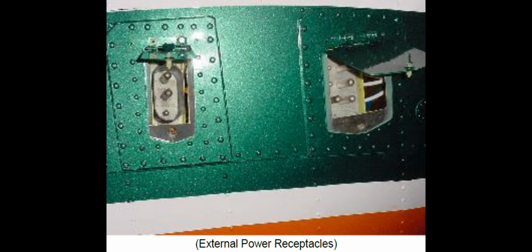If either or both generators are activated, AC bus loads will be removed from the auxiliary power unit and normal power will be restored. If external power does not meet the requirements of the external power monitor panel, a relay in the panel will open, de-energizing the primary and monitored bus relays, removing all aircraft loads from external power.